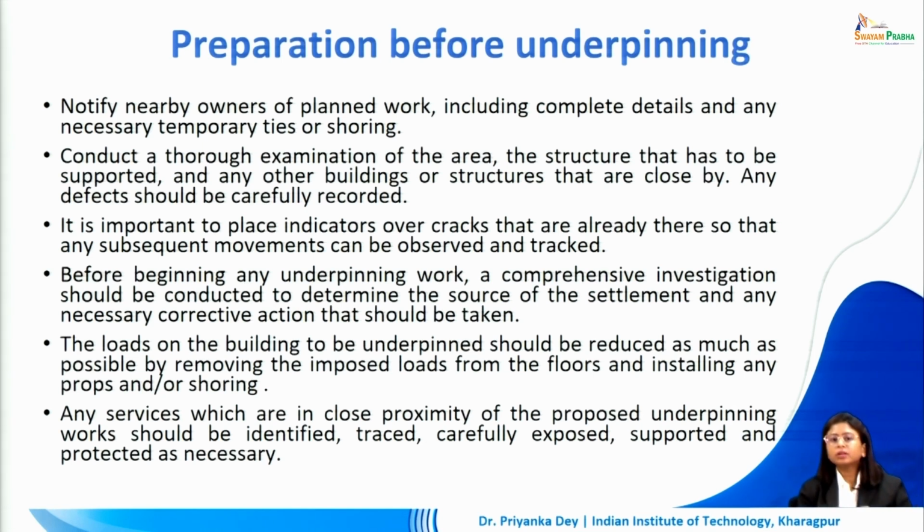Any serious services which are very close to the building, let's say water supply lines or sanitation lines or any other form of services that have been placed very close to the building, we have to identify them, properly mark them, carefully expose them such that while doing the construction work, the masons are very clear about what are the different service lines nearby. Otherwise, accidentally, they might end up damaging it while doing the excavation, trench work or other works below the ground level.